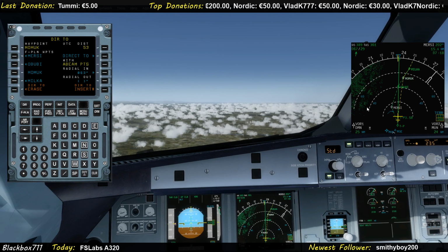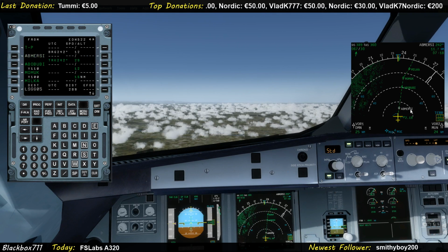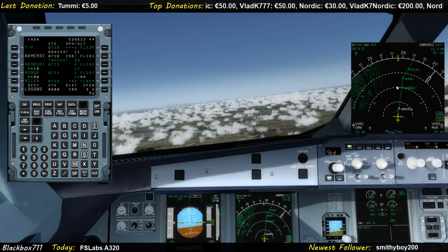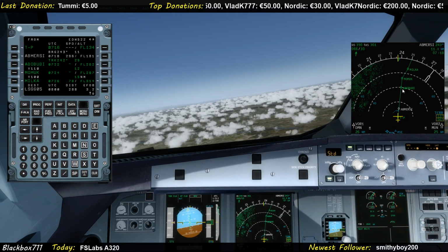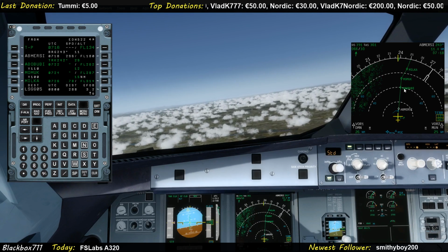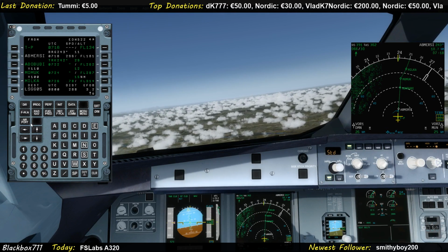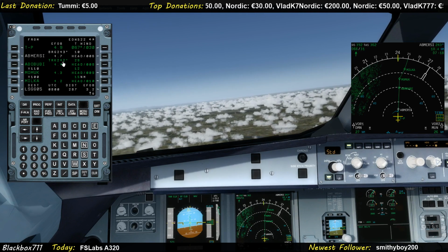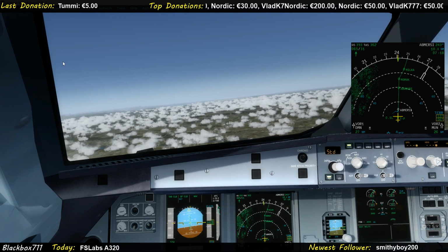the FMS calculates the 90-degree angle to these waypoints on the routing. And now you have the so-called beam points on the routing, and you have a time and also a fuel estimate for these points. So that way you can, you know, do your fuel checks.